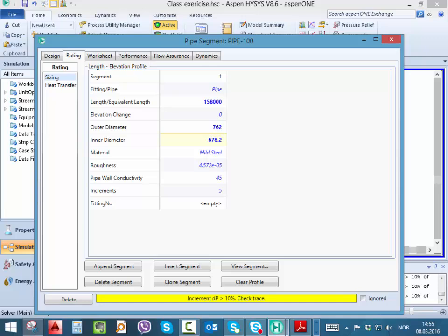Remember that we're going to use average properties in each pipe segment, okay? And if we choose the segment very large, the property that we use is not going to represent very well all the variation that you have inside, okay? So maybe we can use 1,000, and that will give us roughly a section of one.